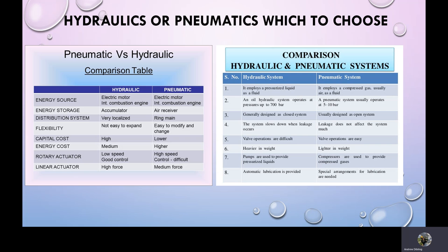So in terms of the fluids, both of them are a fluid, except that one uses a gas in a pneumatic system, and that means that it's compressible. Hydraulic systems are able to generate much higher forces, upwards of 700 bar or 700 atmospheric pressures, 7,000 kPa. Whereas pneumatic systems are generally between 5 to 10 bar. Tools and processes such as that. Positioning, excellent for mechatronics because it's clean.